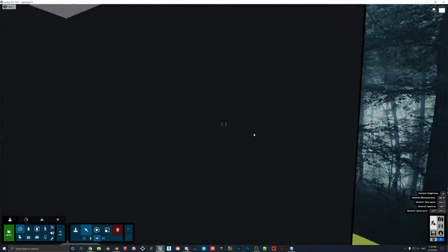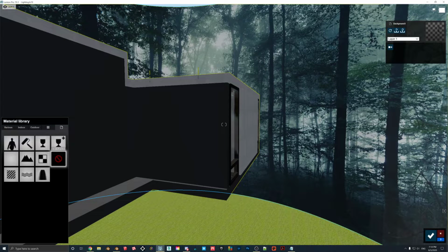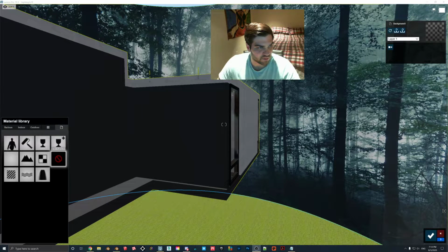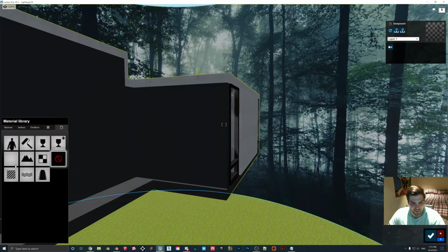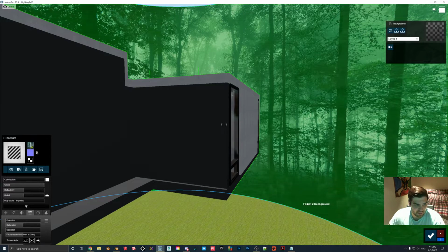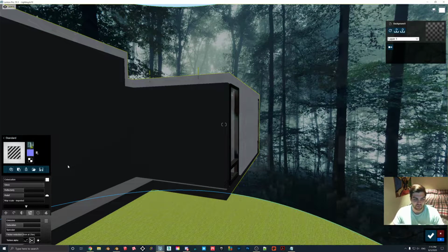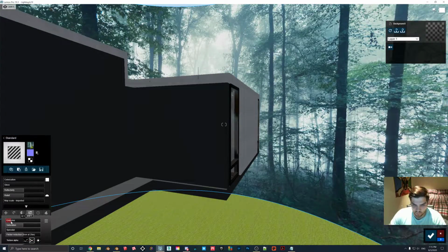It's too dark. So what we're going to do is make this a little bit emissive so that it gives off some of its own color. Now I'll flip this back on for now. I think it's safe to put it down here. Okay, so just make it its own material. I turn the gloss all the way down because if you turn it up, you kind of see the segments. I don't know if it'll pick it up on YouTube, but you can see this glossy effect going on down here because it's not a perfect curve. It may look like it, but it's actually, I think we'll say, 50 segments. So we'll turn this right down, and we're going to turn the emissive so that it's not quite 0.1, just under that.